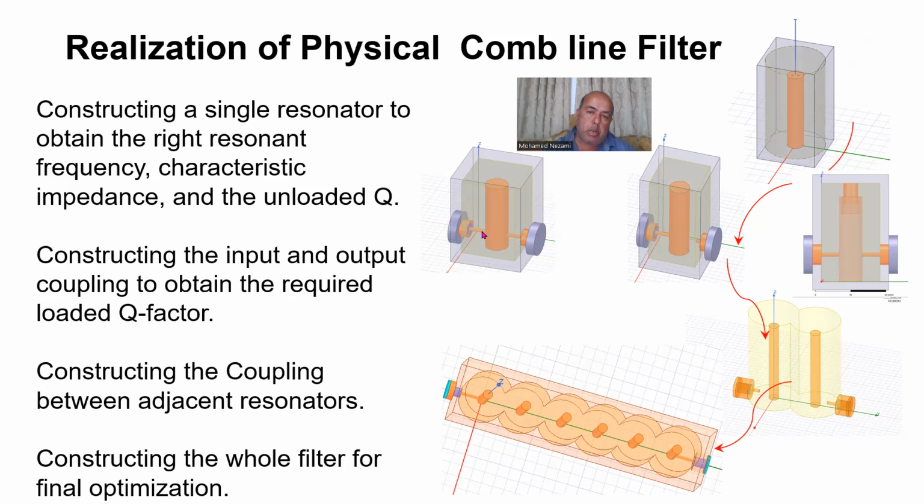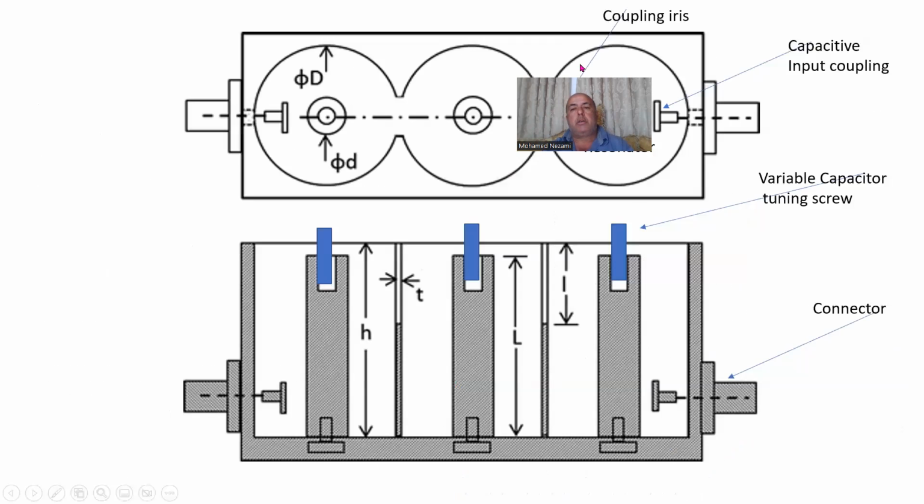Now, one of the things that I forgot to mention is how do you basically match this filter? And that's where this coupling point here, how do you decide on where to tap the filter onto the resonator? And that is done computationally. And then once you do that, you verify it via modeling. So you can come in actually and sweep this distance from the ground end to the inner conductor in here and get a minimum loss, perfect or close to perfect impedance matching.